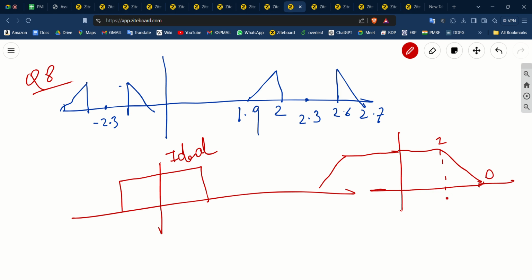So if this is fc, this will be fc plus 1 by alpha, because if the slope is alpha, we saw that the excess bandwidth is 1 by alpha. This changes in alpha amount of frequency, it will change from 1 to 0. So I'll say this is delta f. For clarity, let us show how this alpha is done. Say this is delta f.